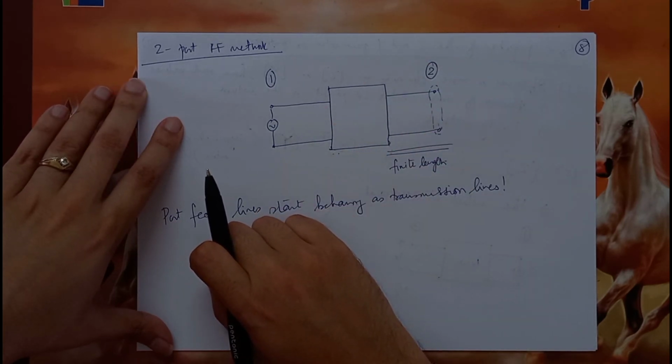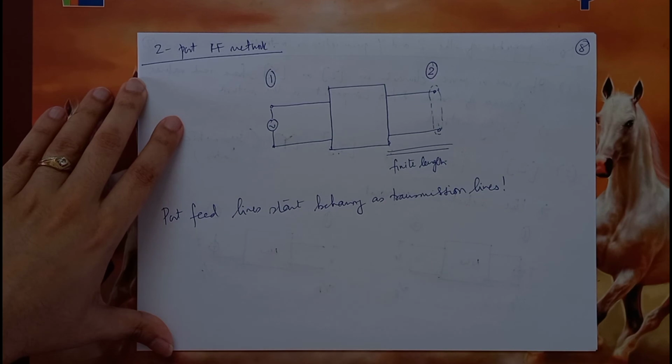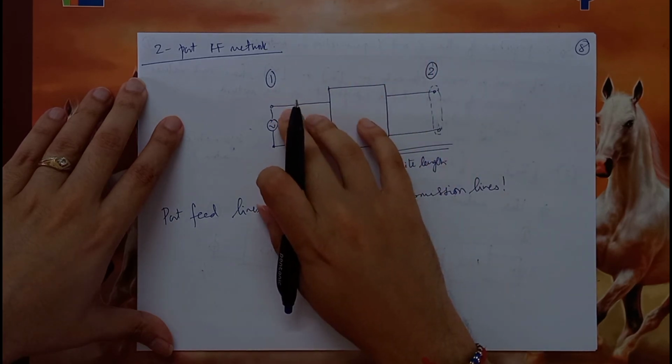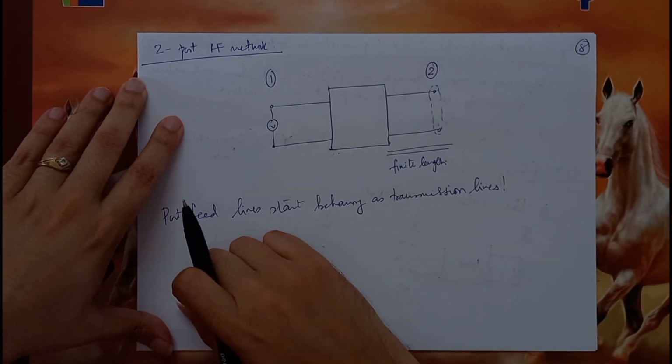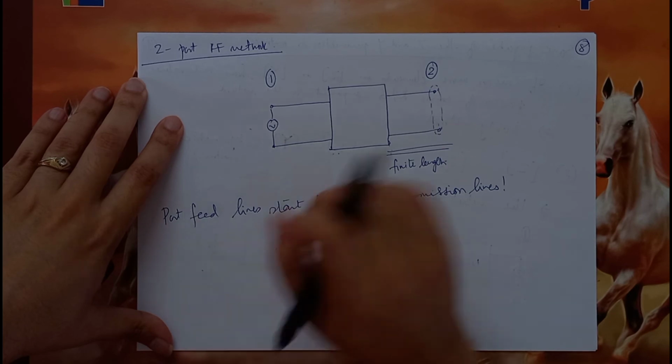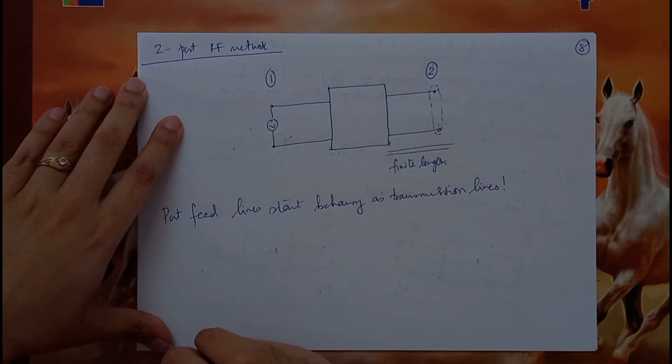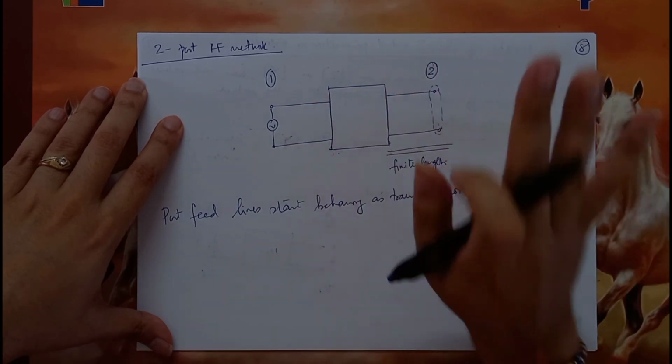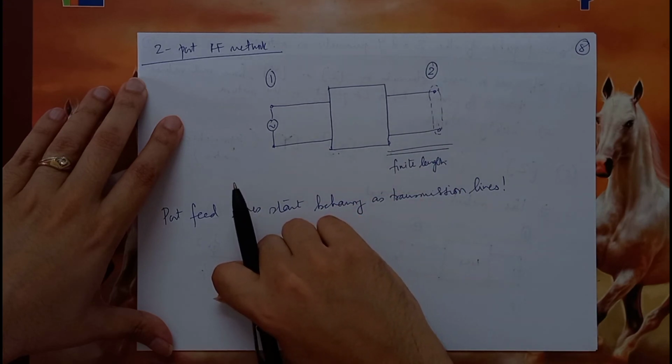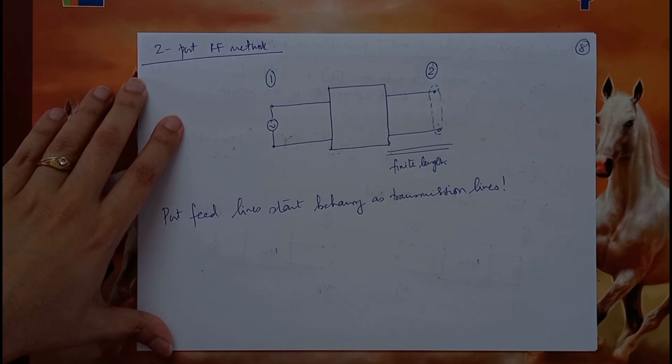Now, this is one of the major reasons why measurement of the Z parameters or Y parameters is difficult at RF frequencies, because the notion of open and short circuit is kind of lost. So, having said that, are there any other problems?